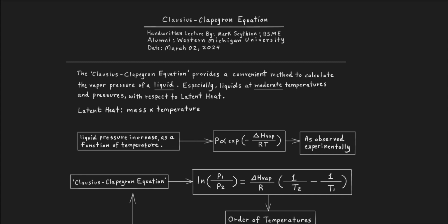So most are reverting to the steam tables with respect to the evaporative state of water at higher temperature and the corresponding enthalpy and energy density involved. So using the steam table to deal with a non-ideal gas such as steam pressure and water vapor pressurization is the standard. However, using the Clausius-Clapeyron equation when dealing with water vapor pressure at moderate temperatures and pressures is highly accurate.